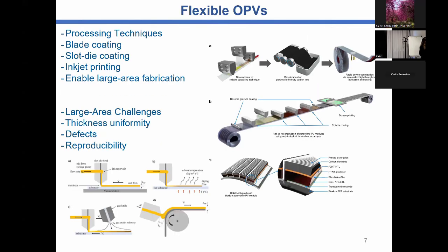In terms of the position, I put here, for example, one overview of the slot die coating. Meniscus coating is this, it's quite hard to see in the picture, but this wet film is formed over the substrate, and the interaction between the blade here and the substrate creates one meniscus that you can spread over the substrate.